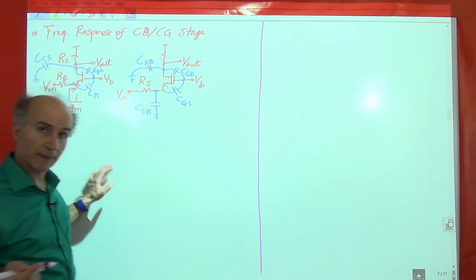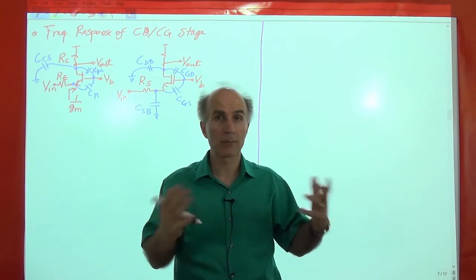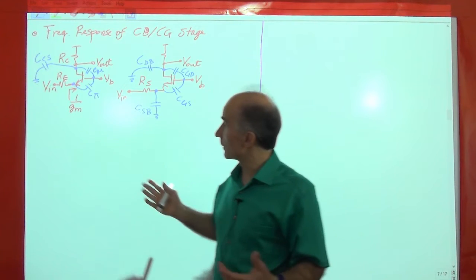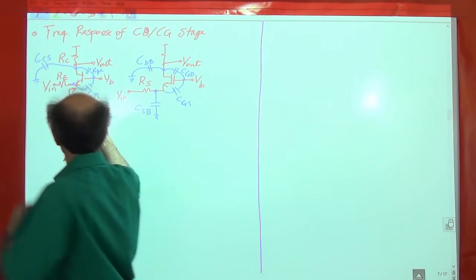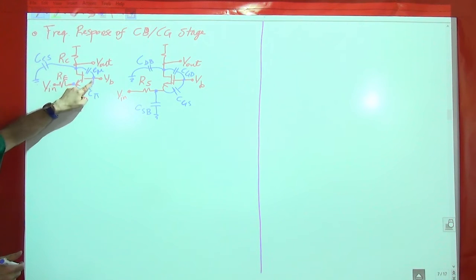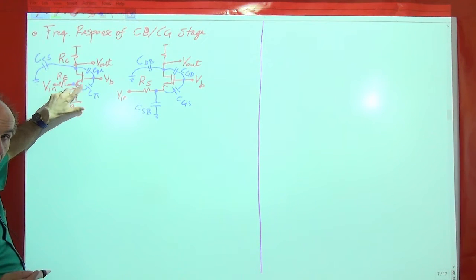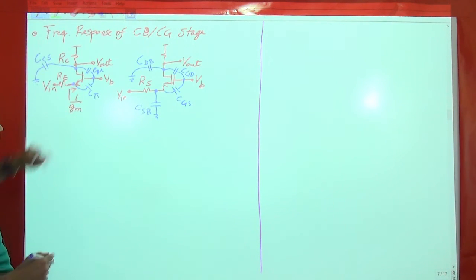In the third step, we said, see if any of the capacitors can be removed or merged to simplify the circuit. All right, so we go and look at these circuits and see what happens. C-pi goes from the emitter to AC ground. But it doesn't merge with anything else. There's no other capacitance that goes from the emitter to AC ground. Okay, no problem. So we'll just keep it like that.